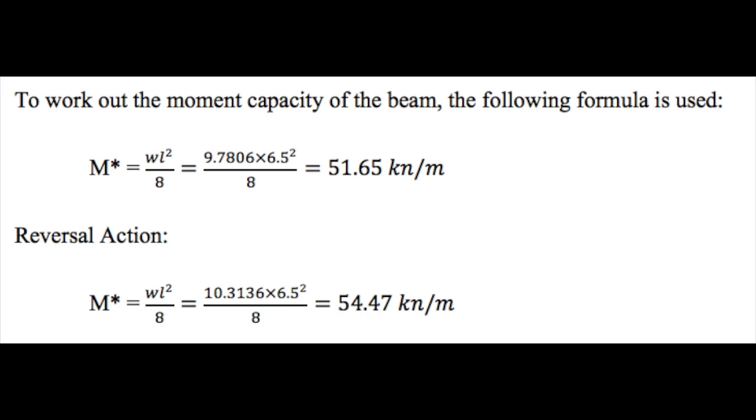When designing the rafters, you must calculate the dead load, live load and wind load. These values will be multiplied by the supported area of the rafter to give a uniformly distributed load on the beam. For the central rafter, that width is 5 metres. The critical load combination is used to find the moment capacity of the beam both under compression and suction, which is used to choose a suitable UB section that is safe and economical. The universal beam section chosen was safe in compression, however not safe in tension. This meant that the use of fly bracing could help strengthen the bottom chord of the beam.